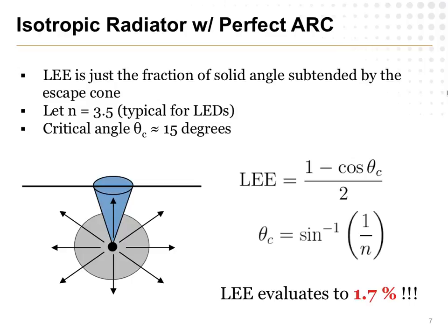So with that calculation, finally, I get a light extraction efficiency of 1.7%. It is about the best I could do if I were to just leave everything alone. So that should ring a few bells. That's obviously very terrible, right? So you can see the scope of the problem for light extraction in an LED. If you can make the most absolutely perfect, internally quantum efficient LED in the entire universe, but you don't treat the surface in any special way, you will absolutely never get above 2% efficiency. All the rest of your energy is just going to be trapped inside and reabsorbed and never seen again.